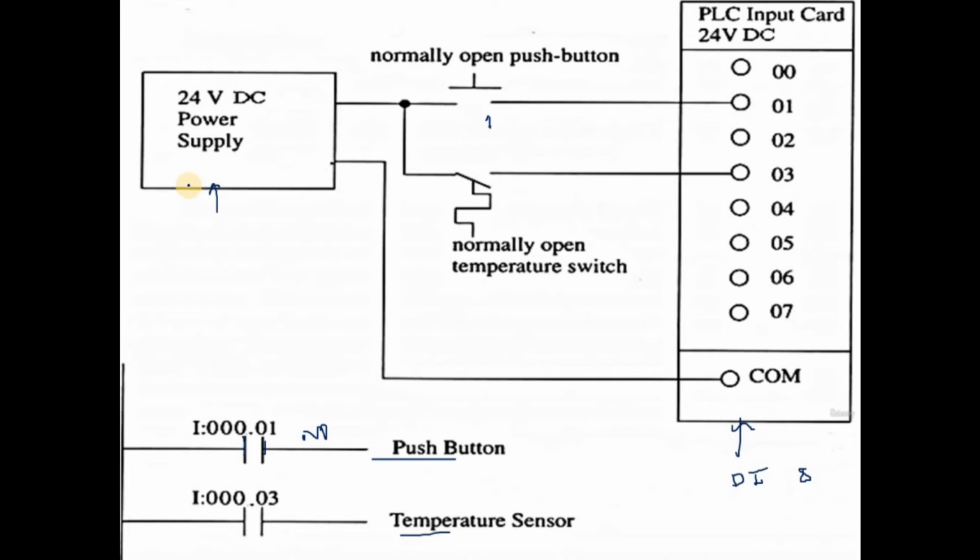As we have discussed in the PLC signal flow, for example, if I'm looking at the address, I'm writing here I colon 1.0/0. Here I is nothing but the file letter for input. One means the slot number. In the upcoming session, I will explain this part in detail. Actually, this address belongs to the SLC 500, meaning the modular type. Just forget it for now and focus on this concept.